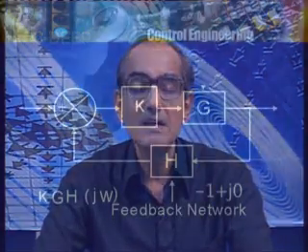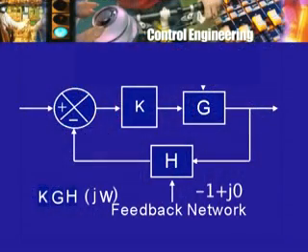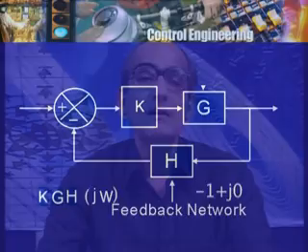We also saw that from that kind of a diagram, we were able to figure out that when we had proportional feedback for our motor control system, H was just a constant coefficient corresponding to the tacho generator. G had two first order transfer functions, the armature circuit transfer function and the motor mechanical circuit transfer function. The system was stable for all positive values of K. There was no question of instability. However, from the root locus method, we saw that the system can become oscillatory.